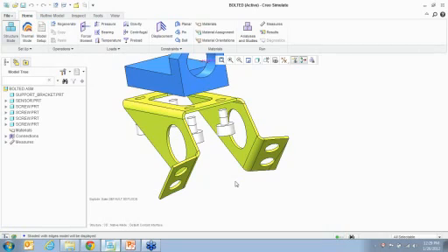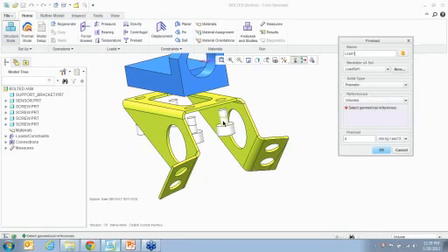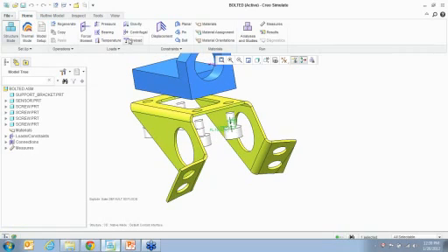Load 1, load set 1, prismatic, volumes. Just go pick that volume region and say there is 1,000 newtons of load on it. It automatically detects the prismatic volume region's axis and determines which direction the load is acting.